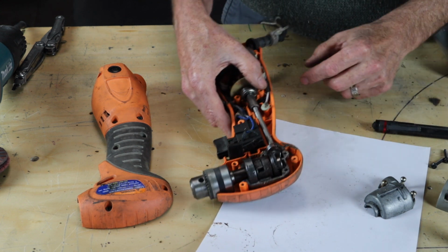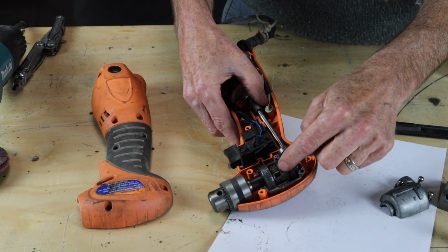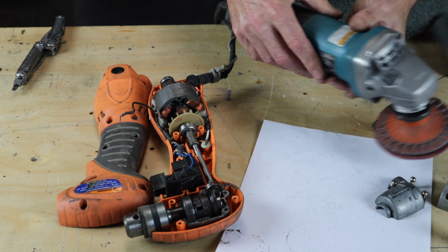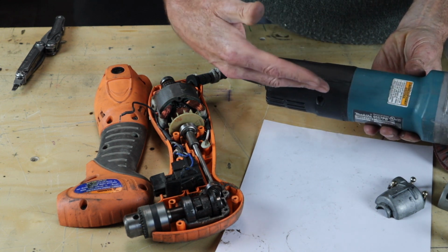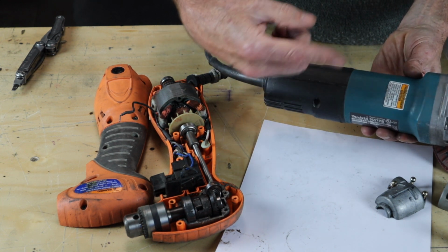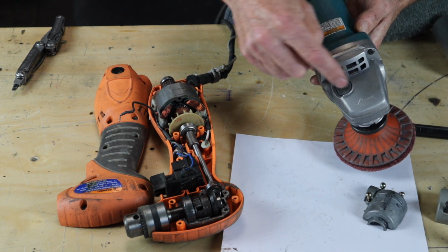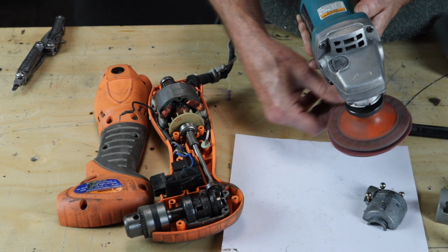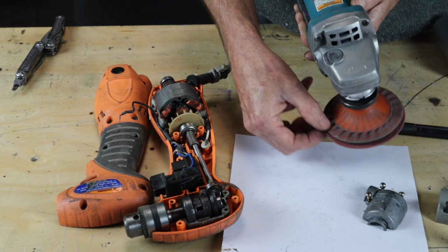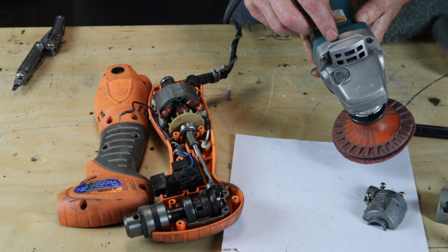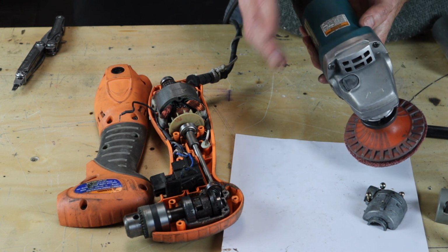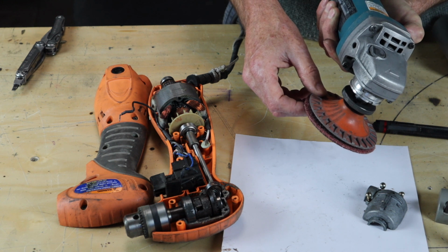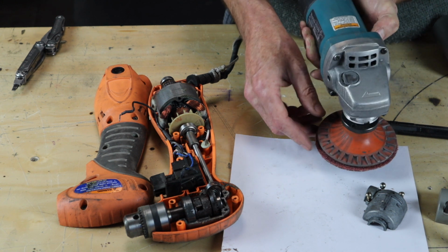But this is the same process that will happen without the planetary gears in an angle grinder. Again, we have the axis of the motor spinning like this, and it comes to here, and then there is a set of beveled gears, so it will drive it 90 degrees into this kind of motion. And again, it will gear it down. So the motor is probably doing 30,000 RPM, and the end result might be 10 or 12,000 RPM. So those are beveled gears.